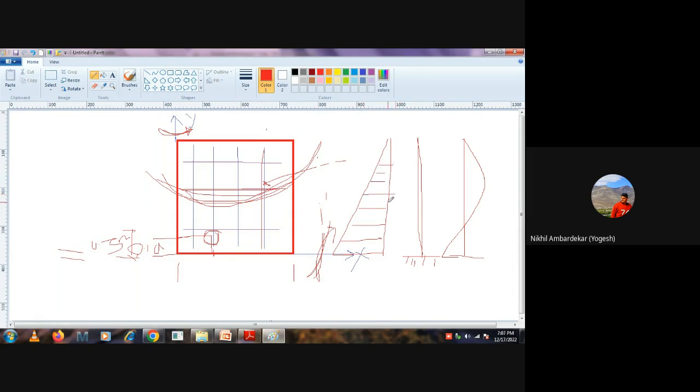So this is triangular pressure for a free top. So what happens? The bending moment will be like this. This is positive, this is sagging, and this is hogging. That's why the negative means we are getting the tension or hogging moments, and this will be positive. That's why we see the difference from plus to minus.